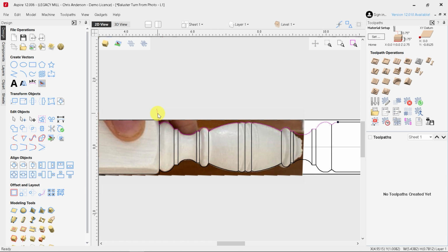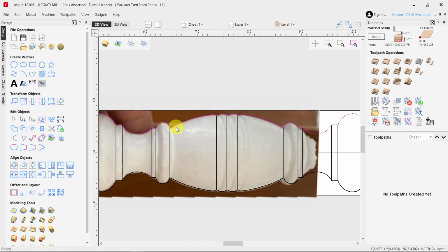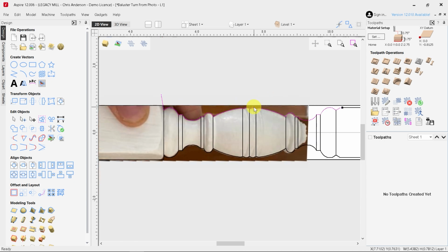The first thing we need to do is make sure that all of these lines are being converted to what are called curves or Beziers instead of keeping them as arcs. For example, when we drew this curve right here, that was drawn as an arc so that we can make it symmetrical, but we need to convert that first. To do that, we highlight the line, and then we come over here to this curve fit, or fit curves to a selected vector tool.